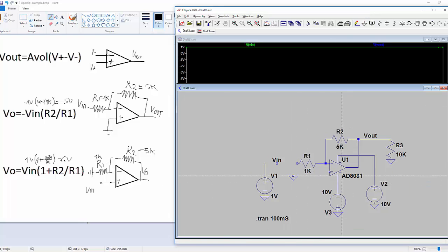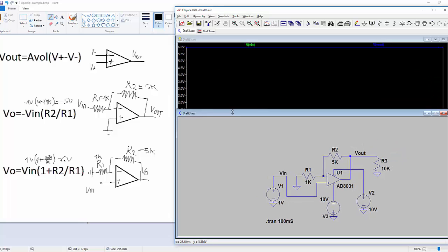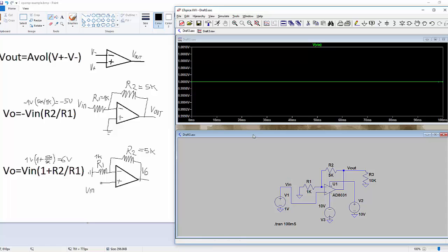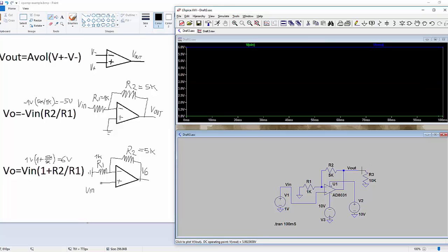We are looking at this circuit, of course, the second one. So we have now the connection to ground here, and the V in, we will take it from here below the ground and now connect it and run it again. So I'm doing the simulation again, and now again looking at V in, it is 1 volt, and now V out should be plus 6 volts, and we are good to go, and we got what we expect.